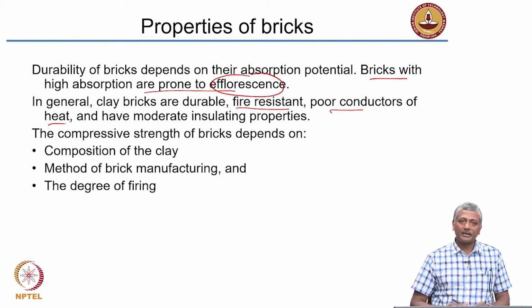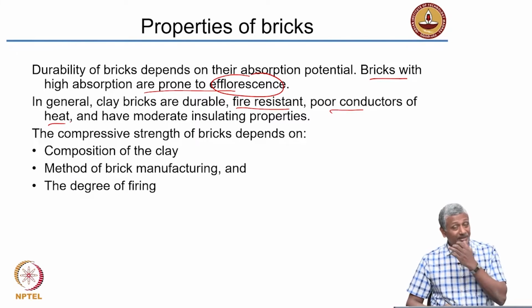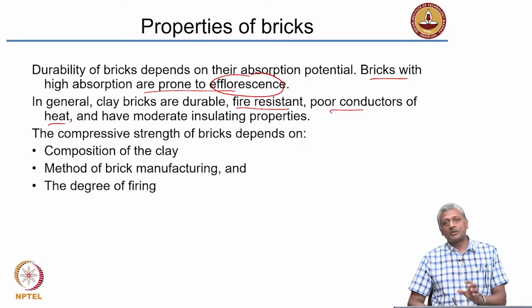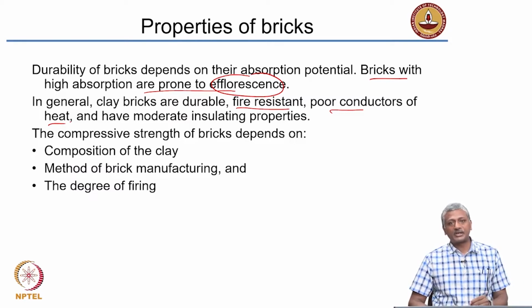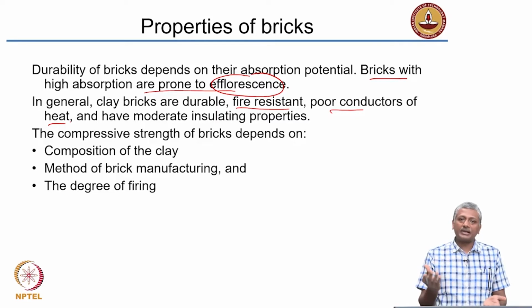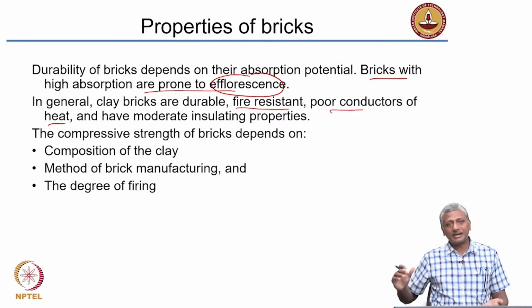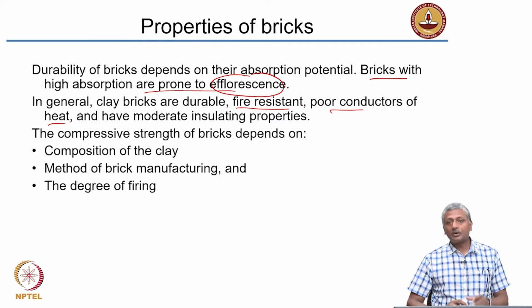Okay, so there are a lot of issues that you need to think about as a civil engineer. It is not just a simple question of which material provides more strength, but you need to use the material that provides all the given characteristics that you need. Just as I said, for a building brick, strength and water absorption are important. For a flooring brick, abrasion resistance is quite important because you have weights getting carried on the surface. So again, all these aspects need to be thought about before designing the material.